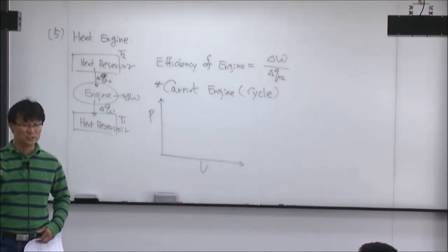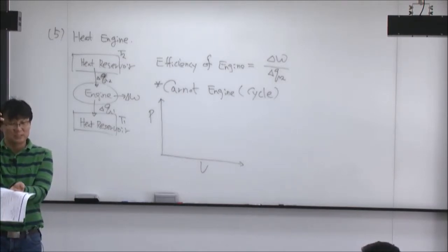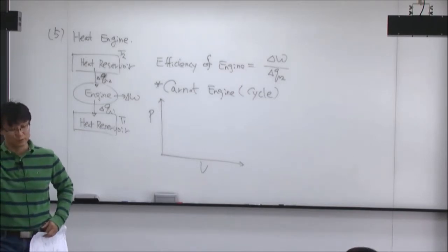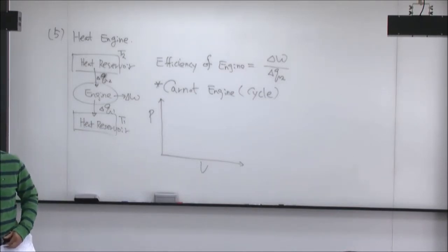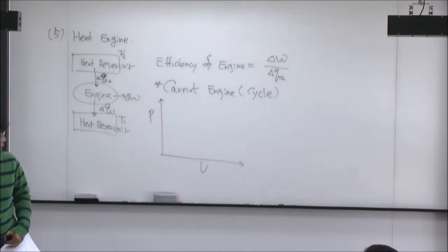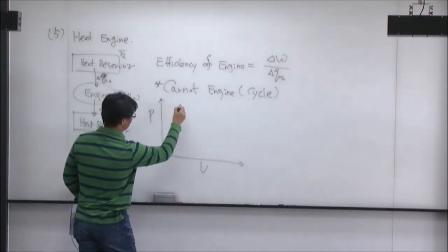And then once that work is finished, it shrinks back again because the temperature of the gas is decreasing, so the volume is decreasing, and you're also releasing the valve, so the gas is going out. So it's expanding and then compression, expansion and compression. This is kind of an engine cycle, okay? And the engine cycle proposed by Carnot is a combination of 2 expansion processes and 2 compression processes, okay? So he explained it in this way.